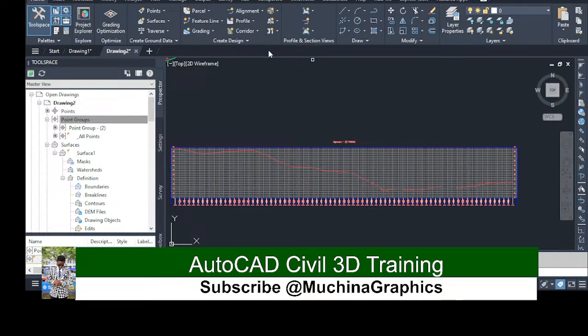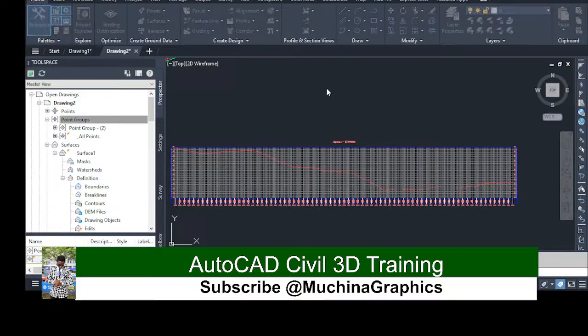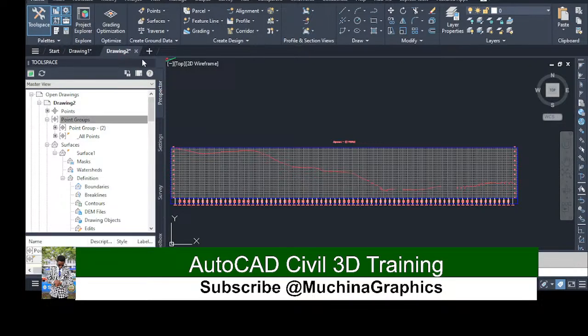I create profile creation tools. So at this time I select this one, and then it will ask me where I want to create it, and then I will select draw tangent with curves, and then I will be able to correct my drawing, since I don't need my road to be very steep and bumpy.